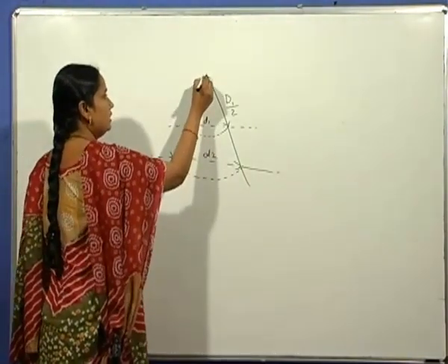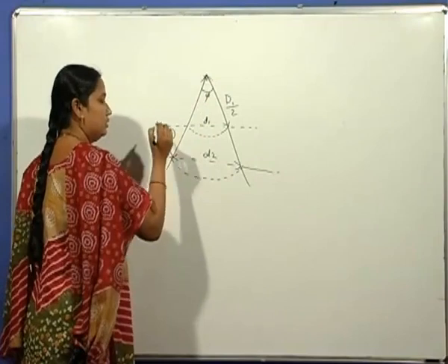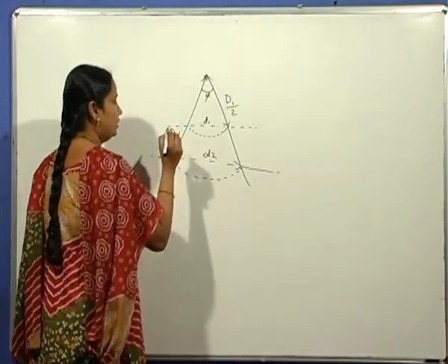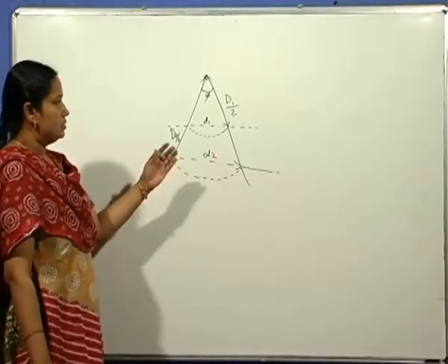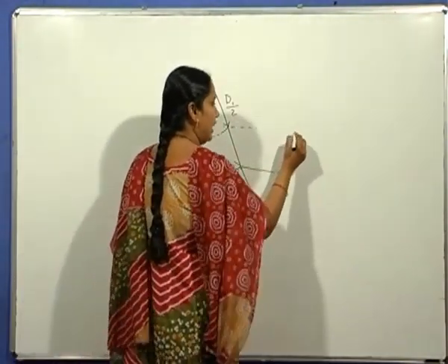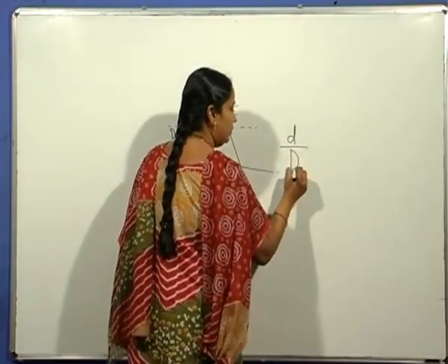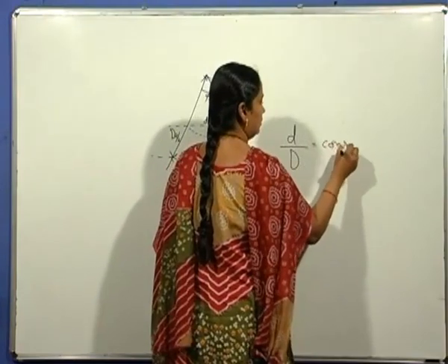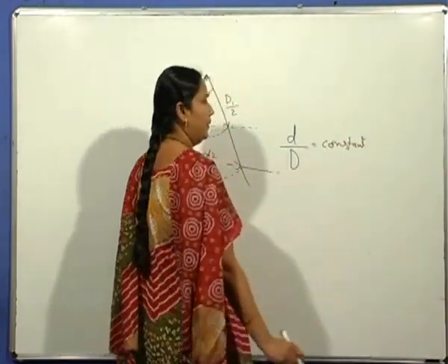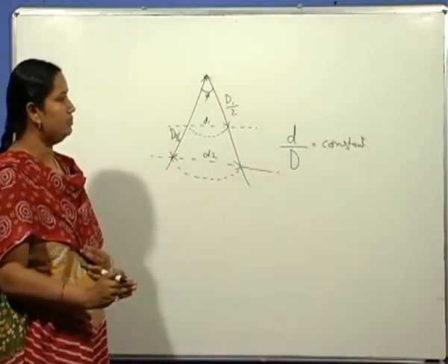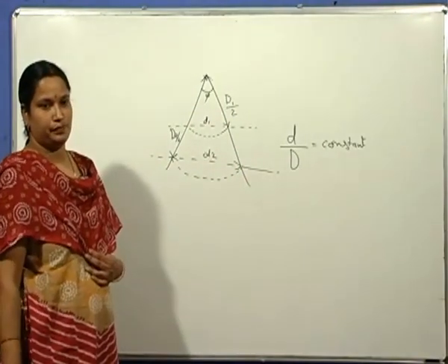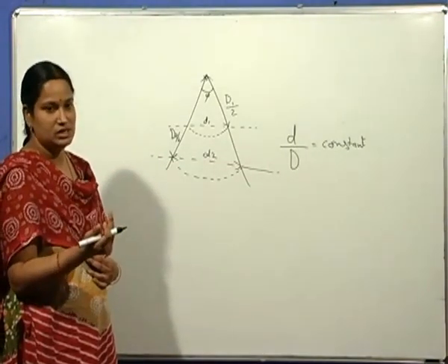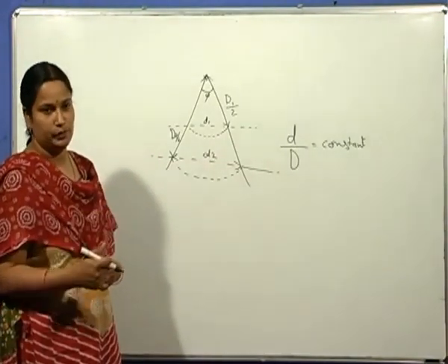when using a different size indenter, that is d2 by 2. So by maintaining the ratio of diameter of indentation to the diameter of indenter equal to a constant, that is, by producing geometrically similar indentations, the hardness values do not vary with load.